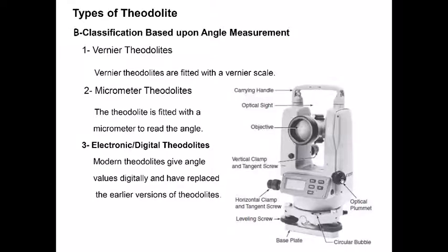This little device inserted onto the theodolite allows you to center your instrument above a station point, which is very important while measuring angles. Earlier, in the prismatic compass, we used to do the same thing using a plumb bob or dropping a stone. In this case, we have this optical plummet that gives you a view of the ground, and that has a reference point so that you can know when the instrument is exactly above the station point.